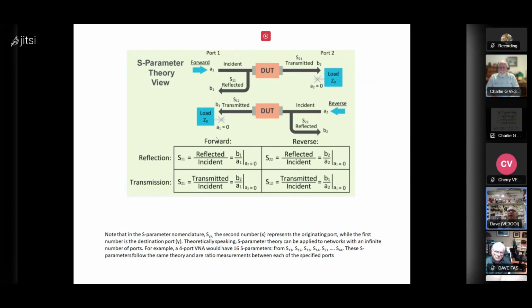Okay, is it possible to take, because the NanoVNA can't do an S22 measurement, but it could do an S11 and an S21. Could you not flip it around and put the output of the DUT where the input goes, and measure what's reflected back to determine the output impedance? I thought about doing that. I tried it and I never got good results.